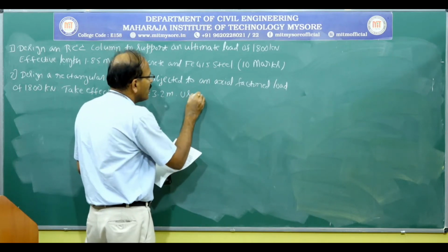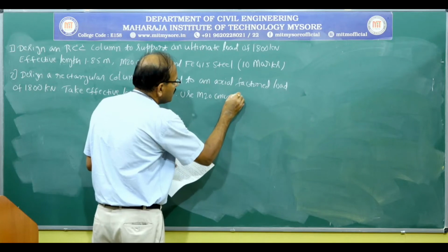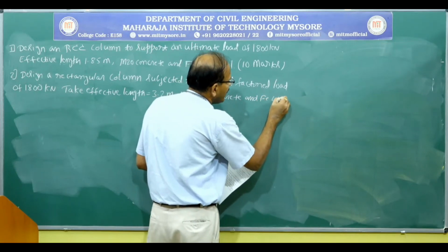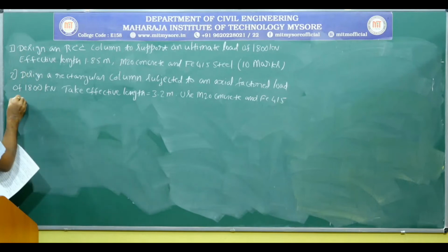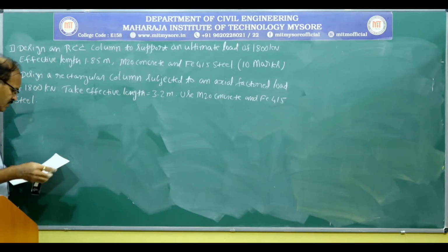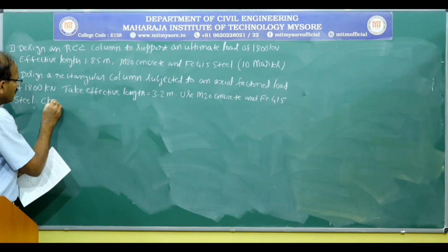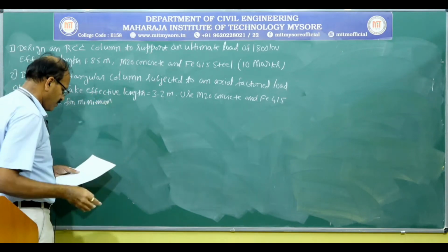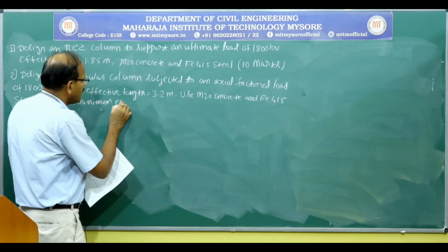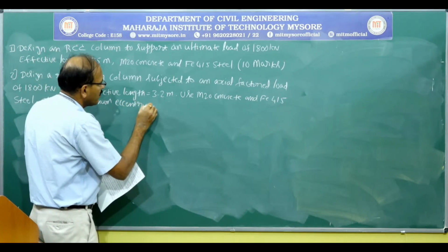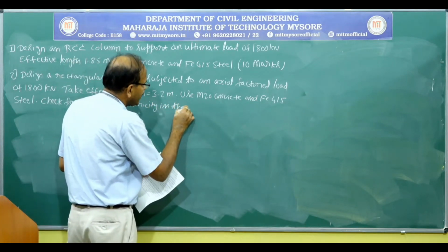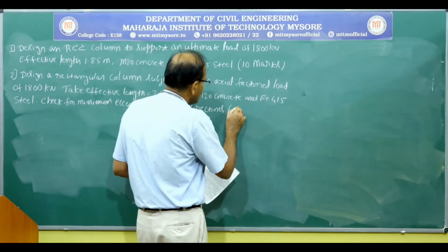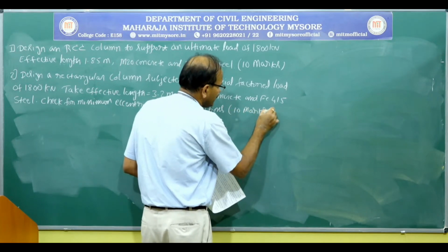Use M20 concrete and Fe 415 steel. Check for minimum eccentricity in the directions. So 10 marks.